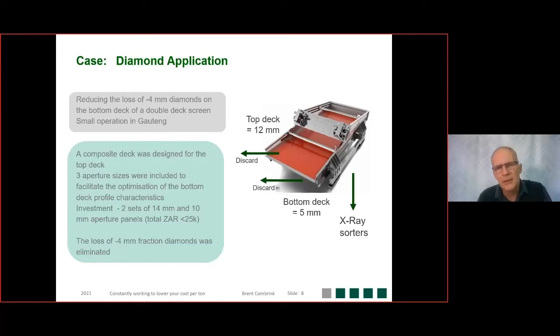I had to think about this for a while, and then there is a certain pattern or profile on any screening material. And typically you can divide that screen into 3 different sections: the feed part, the middle part, and then the discharge side. At the feed end, initially, you will have a lot of material with a thick bed where the smaller particles are struggling to get through.